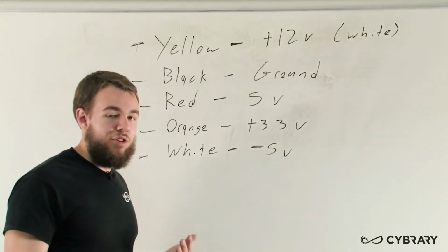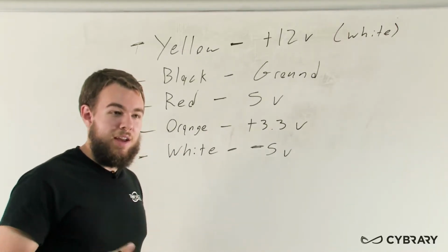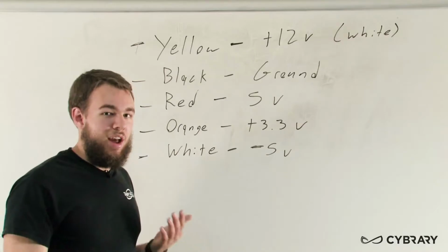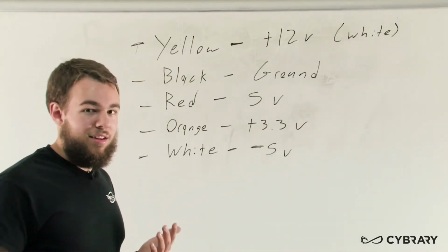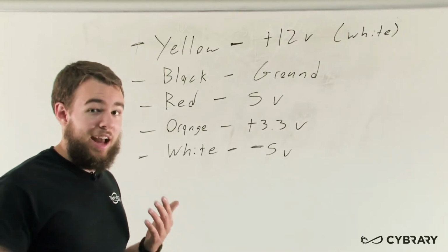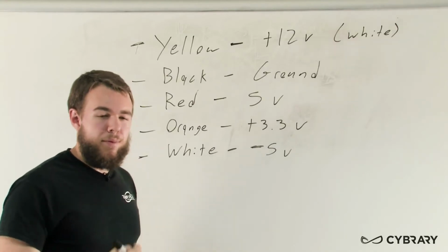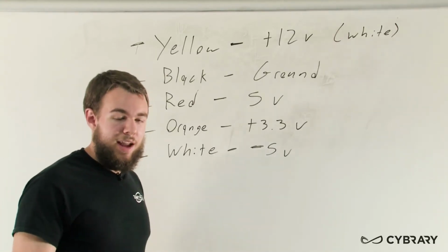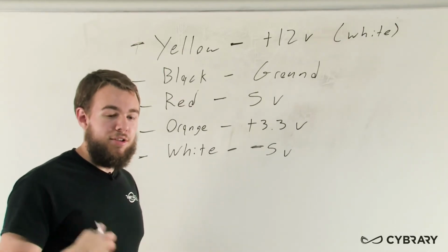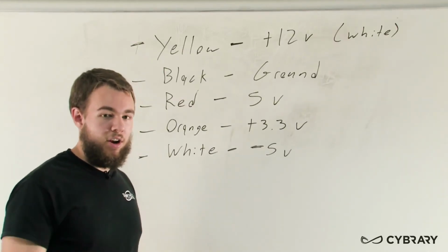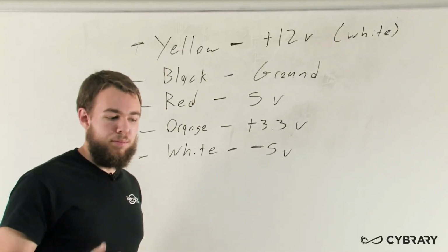So we can choose a lesser voltage fan, or use a voltage adapter to run it on our plus 3.3 volts instead. Maybe you get a little less rotation on that extra fan, so it's not quite as loud. But we don't want to go modifying our system fans, the fans that keep our CPU cool, unless we have a good understanding of the cooling factors inside our cases, because if our computer overheats, it's going to shut down and it's not going to have optimum performance.